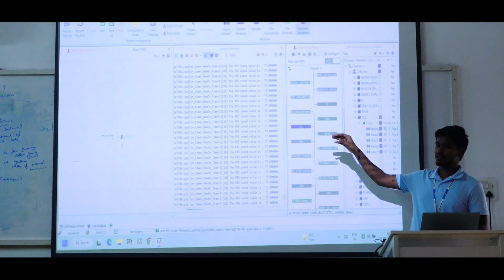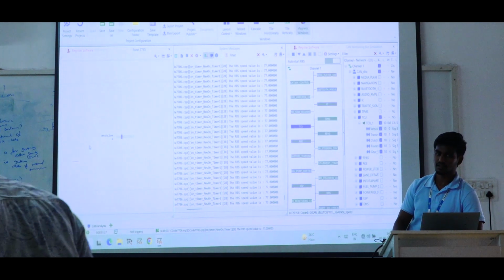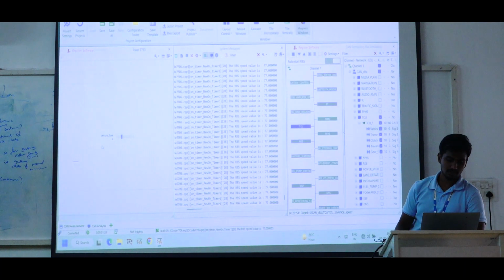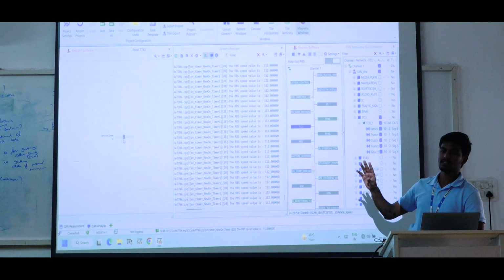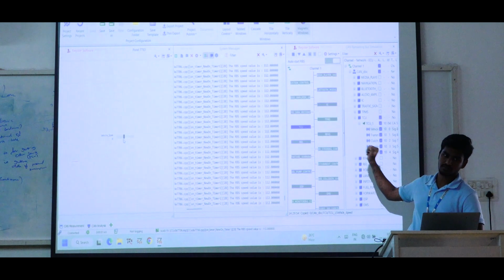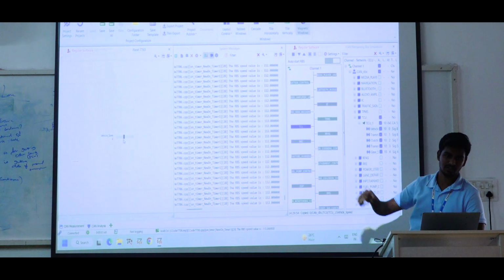We start with get signal value by address. Now you are able to see get signal value by address by using the track bar also. Assume that you are generating a vehicle speed by the track bar. The same thing we receive by CAPL scripting also, but we are not using any hardware, we are not using any transmission window. Instead of that, we are using the rest bus simulation. So it is like a throttle position.